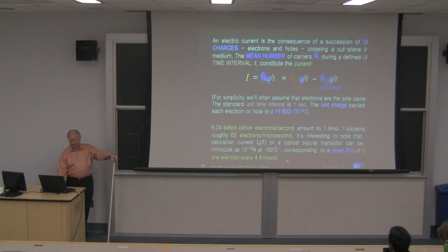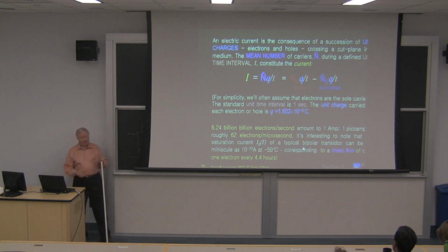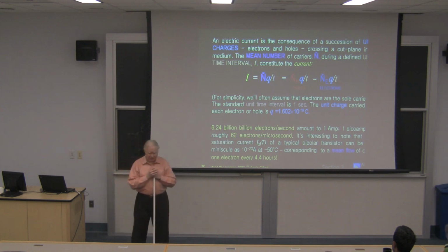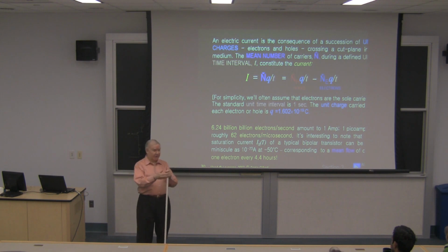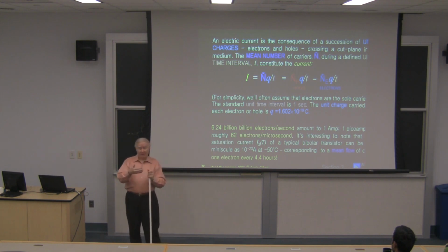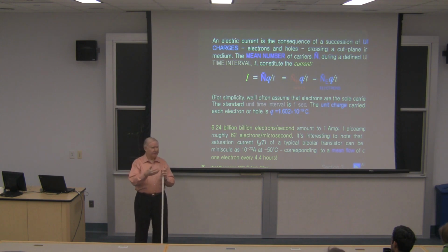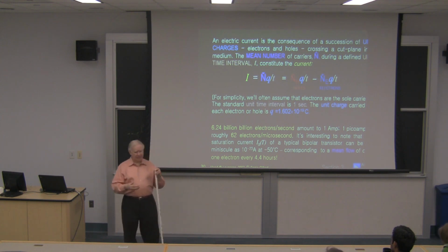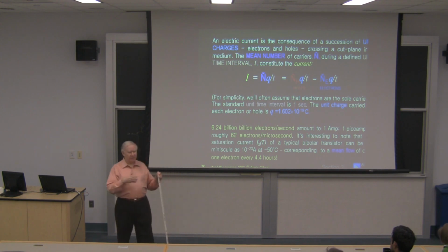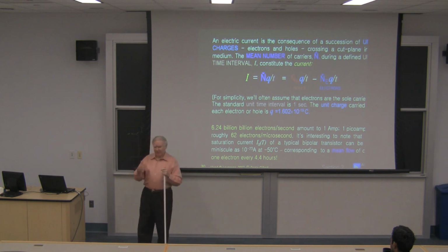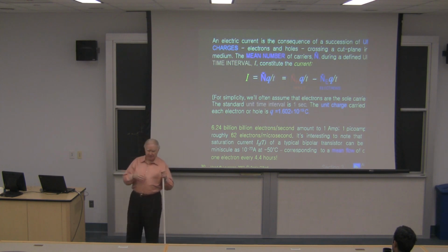If you take I sub S in a bipolar transistor, the saturation current, it's a sort of mythological thing, but it comes out of very firm foundations. Here's the thing to remember. Most of the early work done on semiconductor devices was based on an analogy to the behavior of ideal gases, and so many of the equations of diffusion are based on gas equations. We tend to forget that they had a statistical foundation, and we treat them as if they're scalar numbers instead of time vectors.